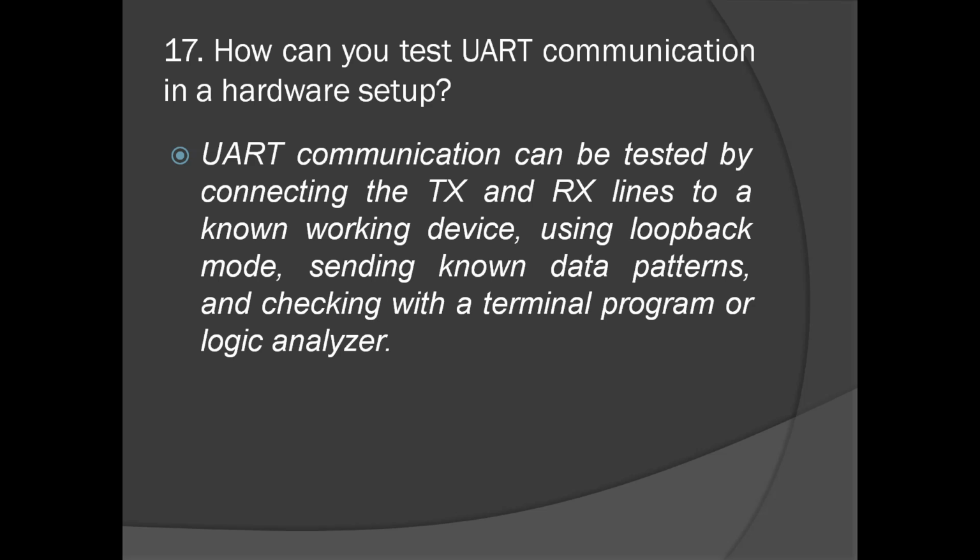Right. Or else what you can do is use a loopback mode in the hardware itself. In that, connect the transmitter line to the receiver line of the same module, and transmit the data. Whatever data you transmit, you can receive. If you are receiving it perfectly, then you can say that particular module is working fine, right?